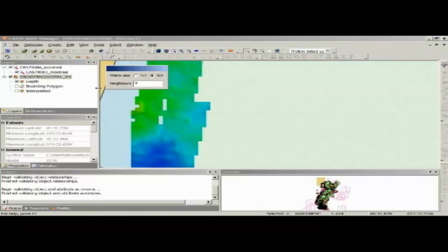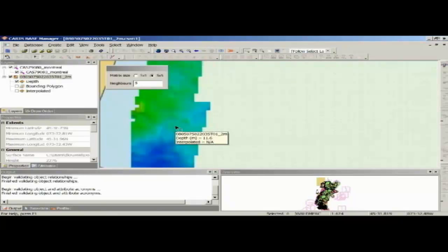Now again, we can use range as well. So we can select the range and select these other 2 holes. This can be really helpful if you want to interpolate holes within your data set where you might have some holidays and it's not as important to go back and resurvey the whole area, but you might have holes that maybe were an island, or maybe you don't want to interpolate it. So this allows the user to point and click around the data set and fill in all of those holes.